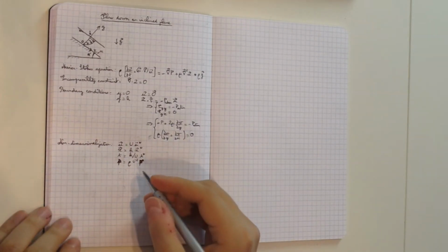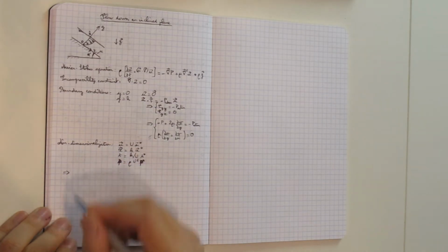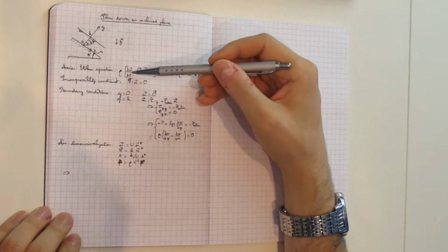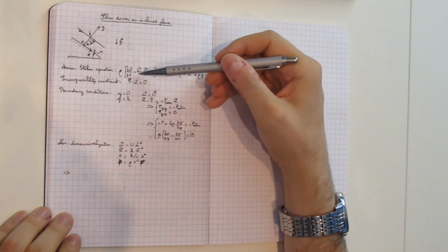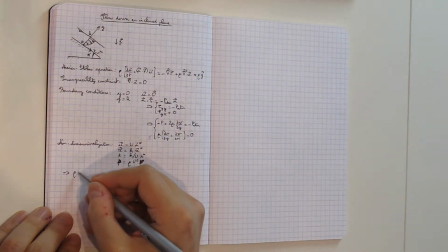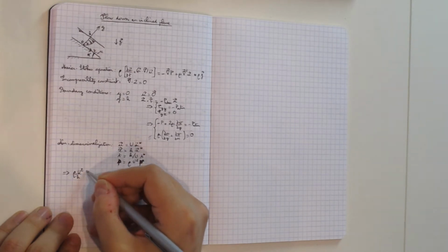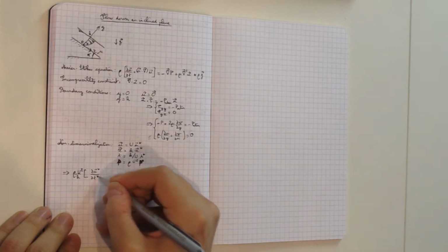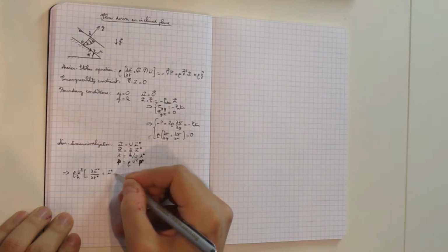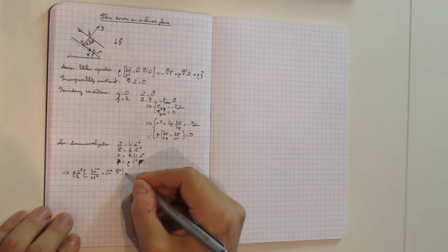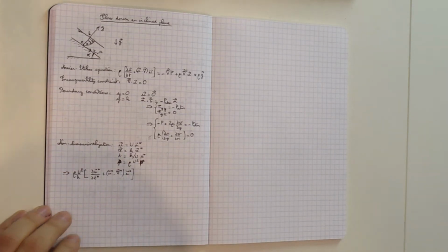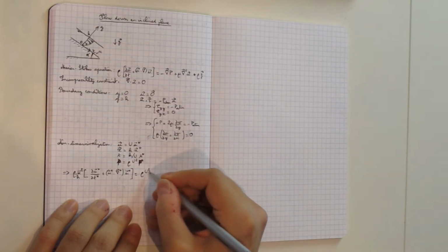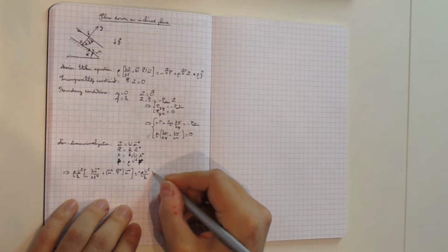So I can now write down my Navier-Stokes equation. By plugging in these scaling quantities, we get rho U squared over h, so that factors out. Rho U squared over h times my left hand side, dU star by dt star plus U star dot grad star U star. And for my right hand side, I've got my pressure gradient here. That's going to be rho U squared over h, with a minus sign coming in, times